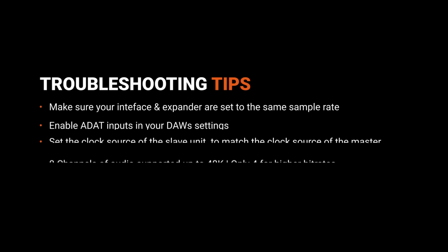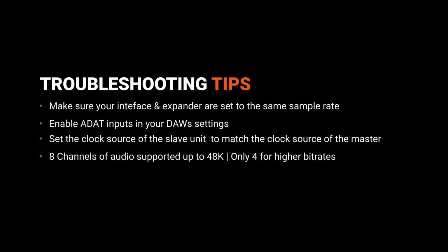If your setup isn't working right away, check these common issues. Make sure both devices are on the same sample rate. Ensure your DAW has ADAT inputs enabled. Set the correct clock source to avoid digital clicks and pops. Remember, ADAT supports 8 channels at 44.1 and 48 kHz sample rates, but only 4 channels at higher rates like